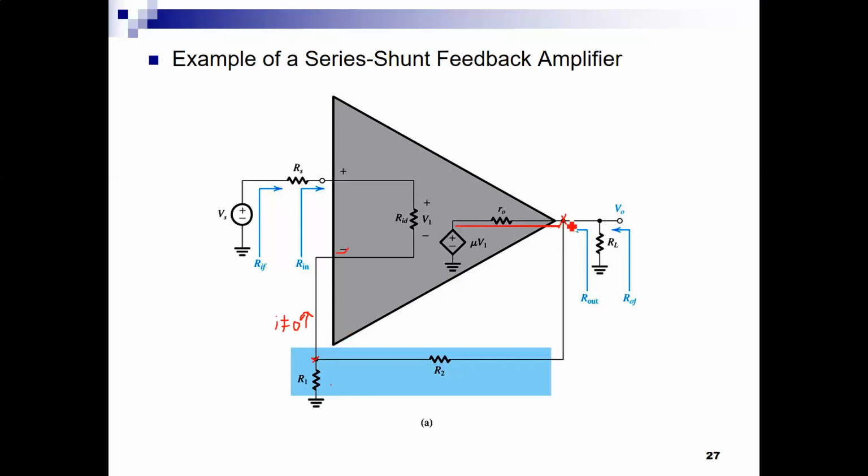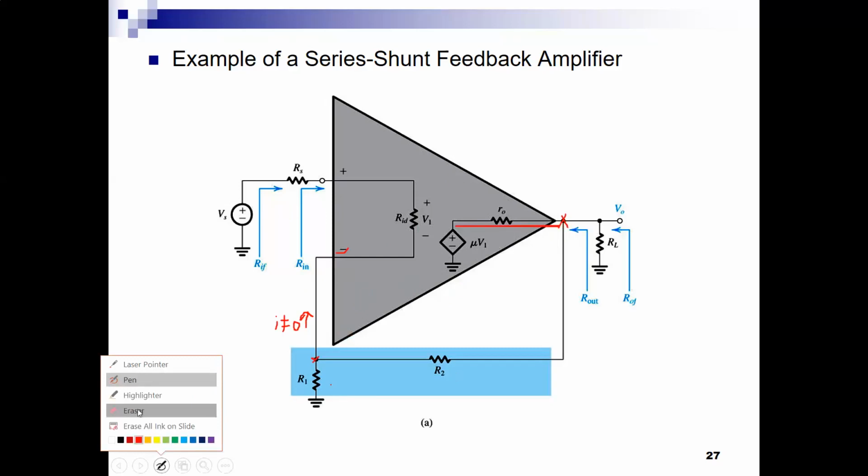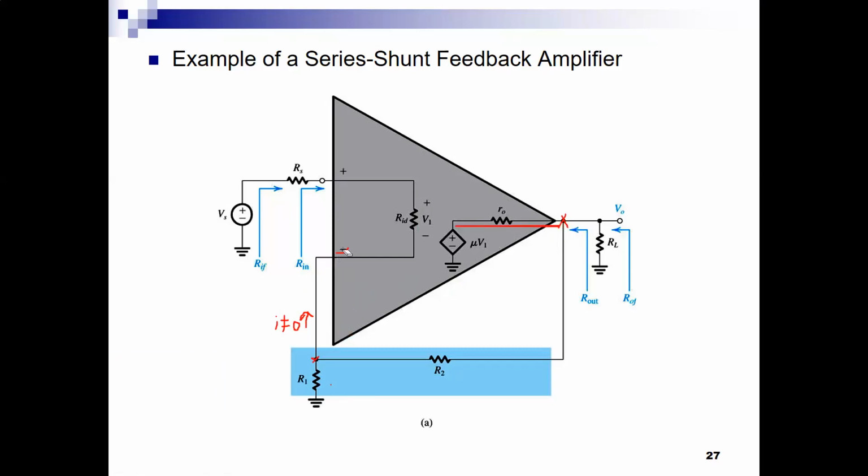It's going to load it, and it's going to affect the current that is flowing in the A block. It's non-ideal. Because it is non-ideal, we have to separate the effects. We need to model what is the load of the beta block on the A block, and we need to figure out what to place to build a modified A block.